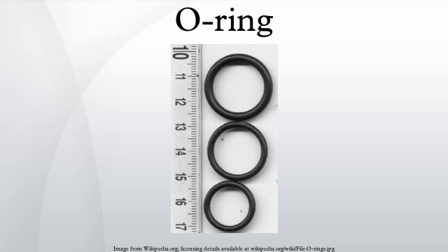Challenger disaster. The failure of an O-ring seal was determined to be the cause of the Space Shuttle Challenger disaster on January 28, 1986. A contributing factor was cold weather prior to the launch. This was famously demonstrated on television by Caltech physics professor Richard Feynman, when he placed a small O-ring into ice-cold water, and subsequently showed its loss of pliability before an investigative committee. The material of the failed O-ring was FKM, which was specified by the shuttle motor contractor, Morton Thiokol.